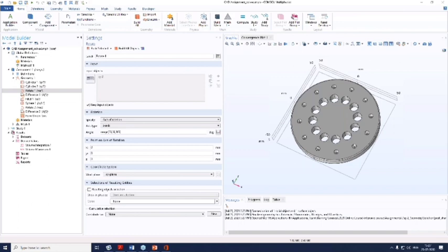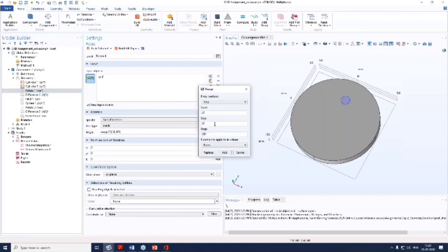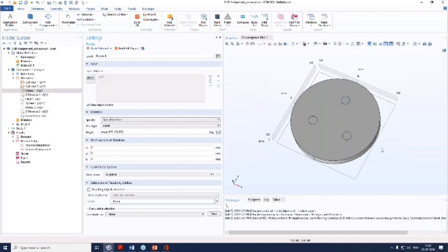Can you please show how to draw 3 cylinders at 120 degrees? Just now I had shown you how you can have these cylinders drawn at different angles. Here in this case the cylinders are drawn at intervals of 30 degrees. If you want, you can change that step size as well. Let's say if I mention it as 120, 120, 120, replace, you can see that this is how the cylinders can be drawn.